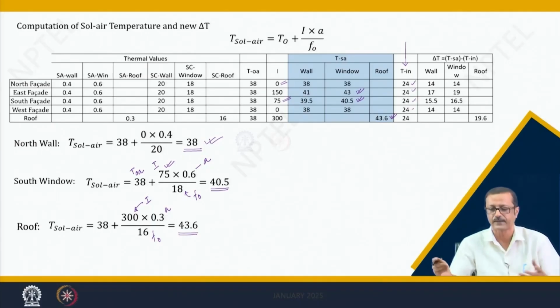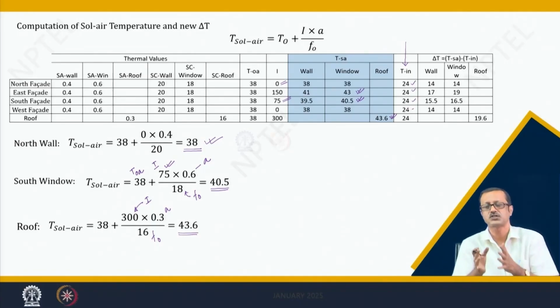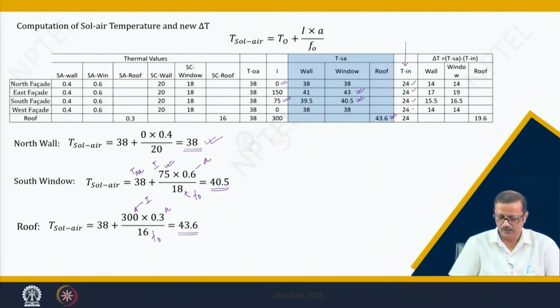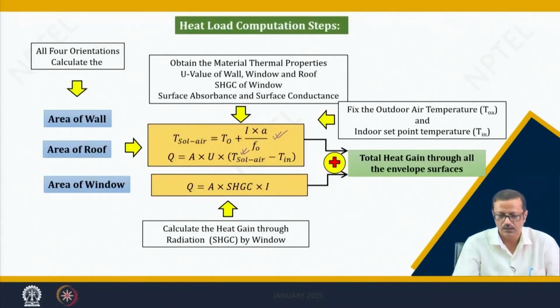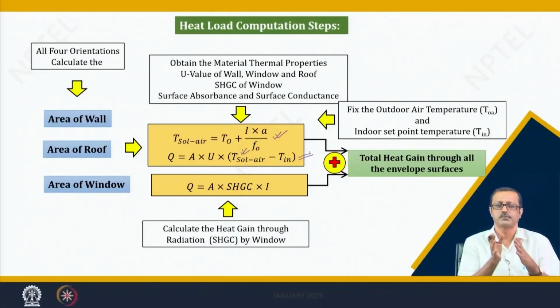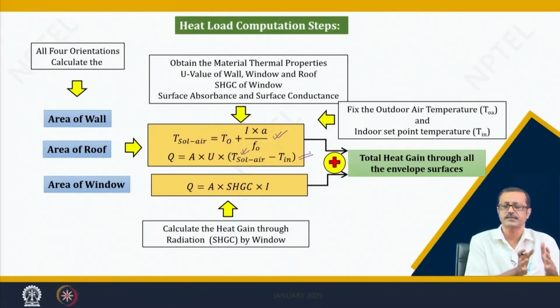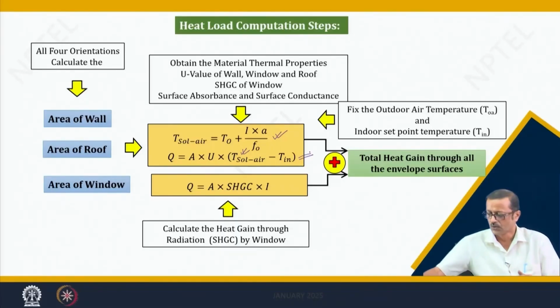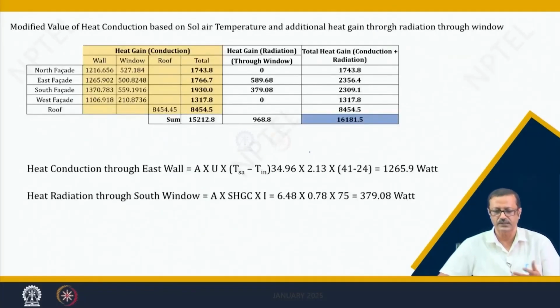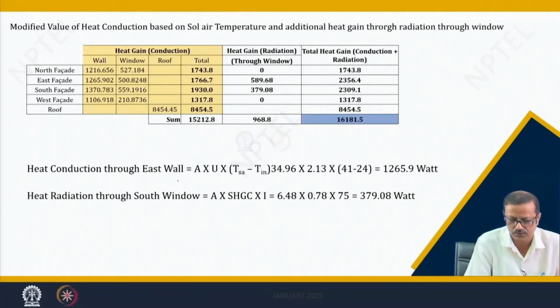Your delta T will now change for the wall, the windows and the roof, and everything has to be taken into account in this equation, where everything has to be multiplied by the corresponding surface area and the U value. With Excel we can do it very easily.